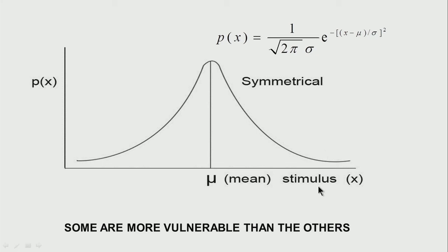And when we say overpressure causing the damage, we can say overpressure is something like a stimulus which causes this. Therefore, it is more reasonable that we represent the effect of the stimulus, being overpressure, as a distribution like this, wherein more number of people or more number of buildings are affected near the mean. Buildings also have some statistics because the material of construction is not the same.